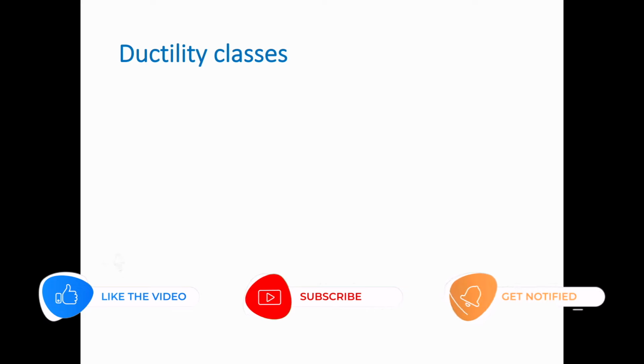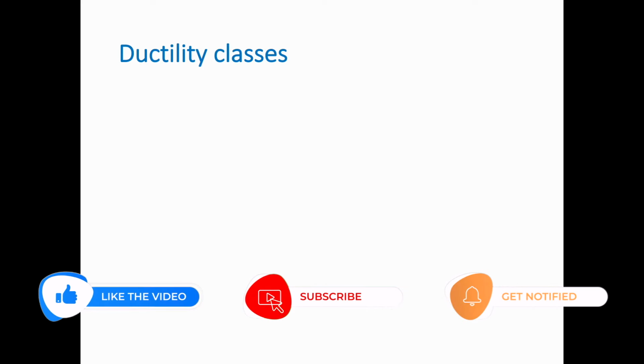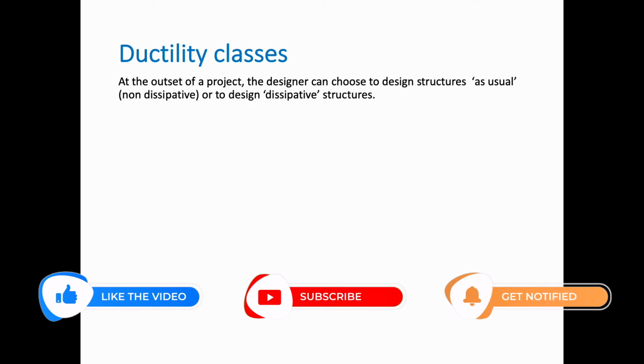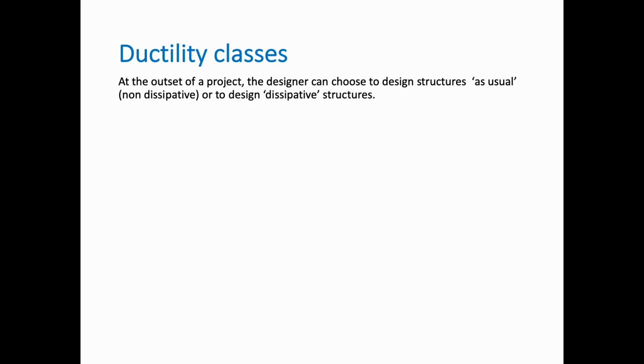So the first thing that the designer has to do is to classify the structure in terms of ductility. At the beginning, you have to choose whether this structure will be designed as a non-dissipative structure as usual, or as a dissipative structure.